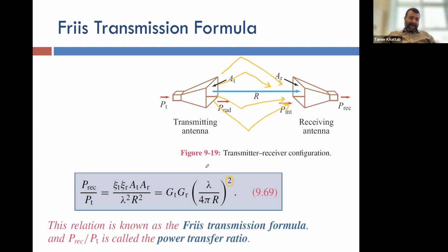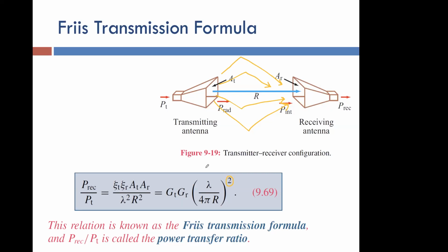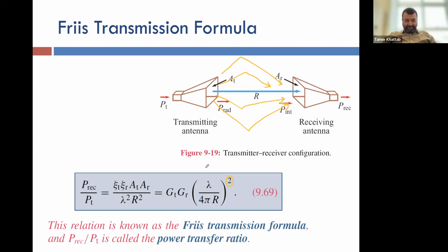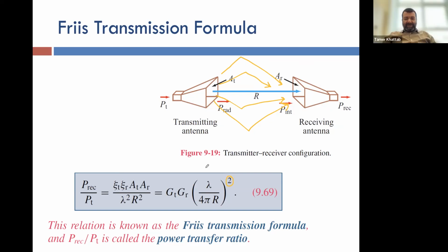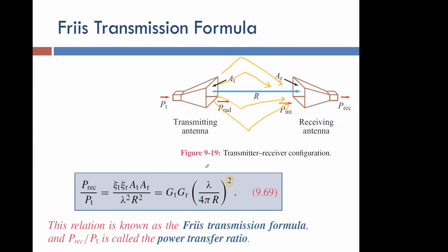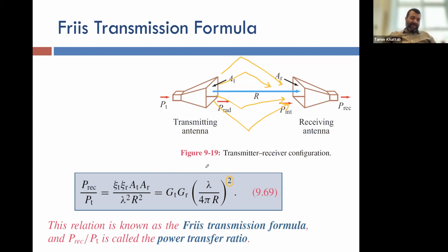Any other questions on this before we move to the next topic? So here, the way we compensate for the path losses is just changing the exponent on the path loss? Yes. Okay, so we don't need to do channel modeling in this case, at least. That's channel modeling, but channel modeling has many stages. We are here only looking at something called the path loss. The other stages you are talking about are probably things like what they call small scale fading variation.